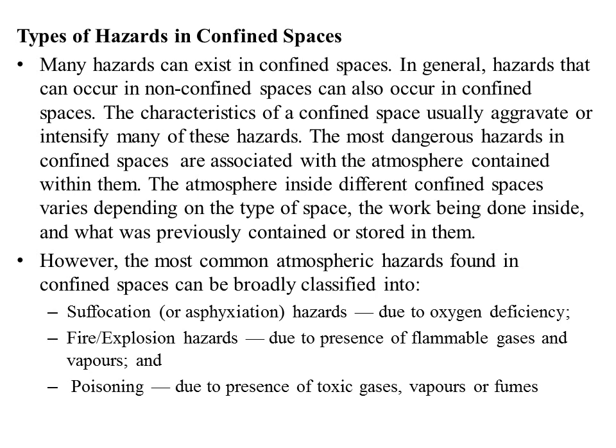Let us see the types of hazards in confined spaces. Of course, there are many hazards that can exist in a confined space. Some of the hazards that can be present in non-confined spaces can also occur in confined spaces. The most dangerous hazard is the atmosphere contained within them. The atmosphere present inside a confined space will vary depending upon the type of space, the work that is being done inside, and what was previously contained or stored in that confined space.